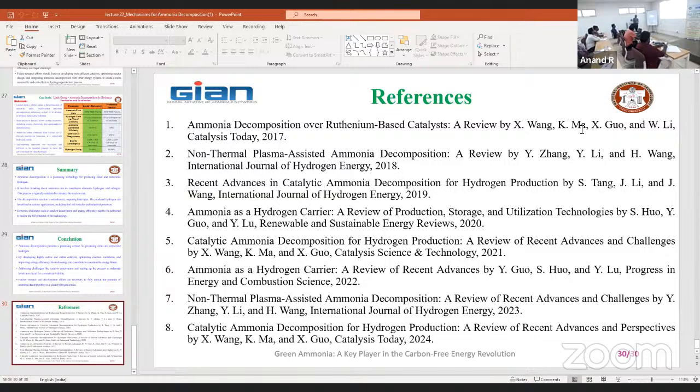We need to try with diesel as per the IS standard. You need to run for 500 hours and take out all the components exposed to the diesel or combustion products. Then we can put the tribological study on all the components, starting from aluminum, cast iron, copper, everything. We tried with biodiesel actually. We ran it for 500 hours with diesel.